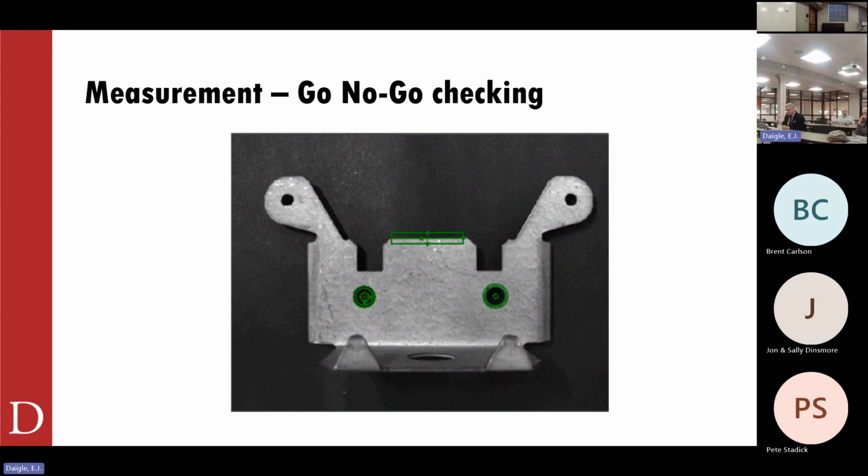But we can do that with machine vision, 100%. We do every single one. The only trick though is it's important that we are calibrated to units at that point. It's not enough just to take a snapshot. We do need to calibrate to units, so we need something that's going to allow us to calibrate to units at that point.